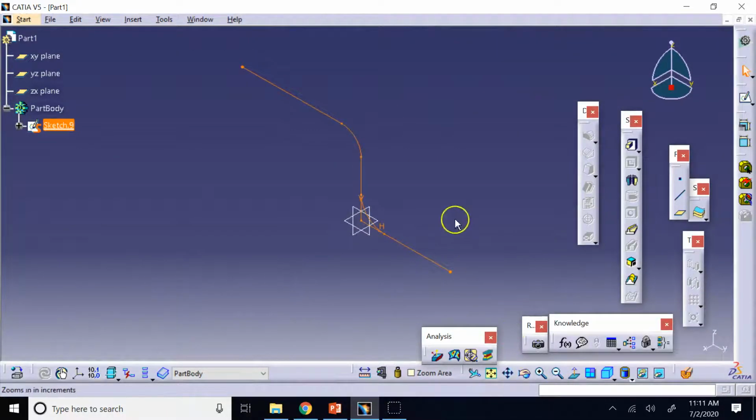Okay, then now I want a circle to follow this profile and create a pipe for me, right? Or a hollow circle and follow a pipe and create a pipe for me. So this you cannot do with Extrude because this guide profile is clearly not a single line. So in order to do that, now that you have the guide profile, now you need the sweep profile, the one that you want to follow this path.